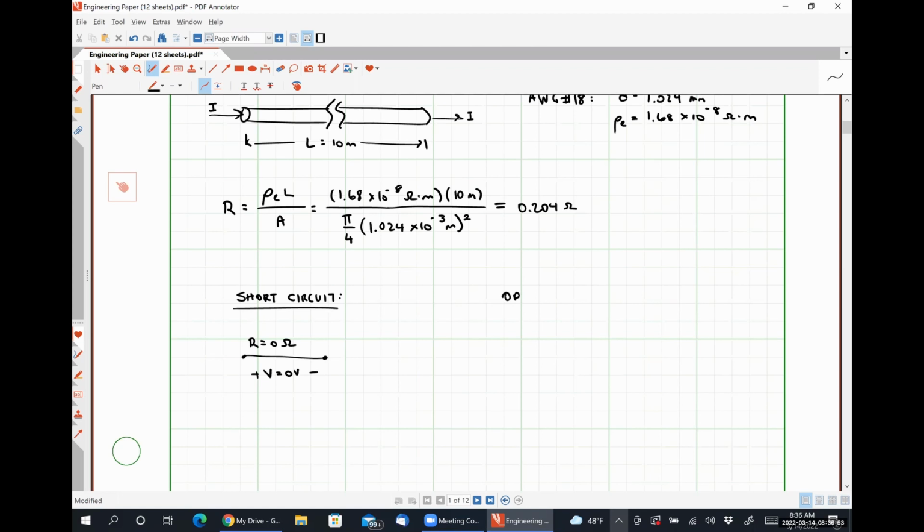An open circuit, which is literally just like a break in a wire, we will represent as follows. We have a piece of wire with a gap in it. Since there is a gap in the wire, the current that flows through the open circuit must be equal to 0 amps, which means we can treat this as a resistor of infinite resistance.